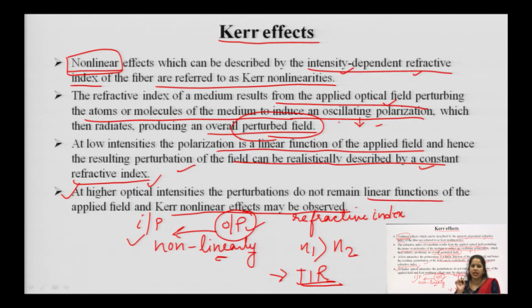So, we can easily say at this particular instant that if we want to reduce the Kerr effect in any sort of optical fiber propagation, then we have to maintain the intensity of optical light low. We should not increase the intensity of optical light, because the effect is most prominent in the case of a higher intensity of optical light. At low intensity, its value is relatively negligible, or we can say low.